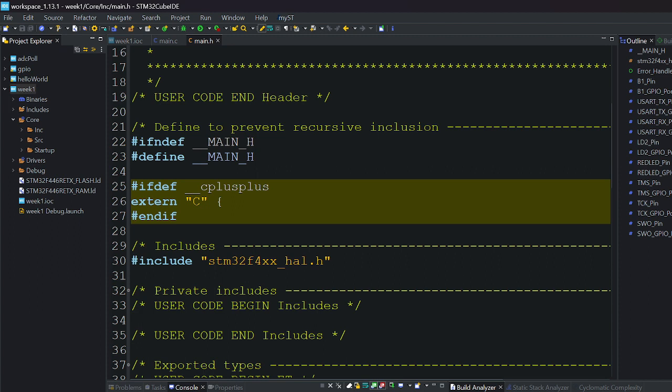Any of these preprocessor directives, I can make one and say if def TFT, or you might have an if def debug or something, and include or exclude code. I'll often put in what type of TFT I'm using and link in the code for the different initialization for different LCDs. So I will put into the properties in some of the settings just a name. I'll call it ILI9341 for the display that you have. I might have different displays, and I want to have all the code in one and just say what LCD I have and link in the appropriate initialization files. Okay?